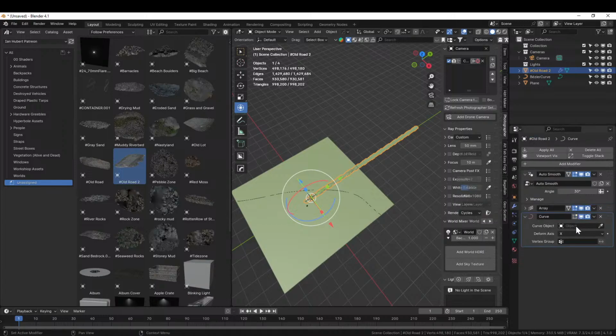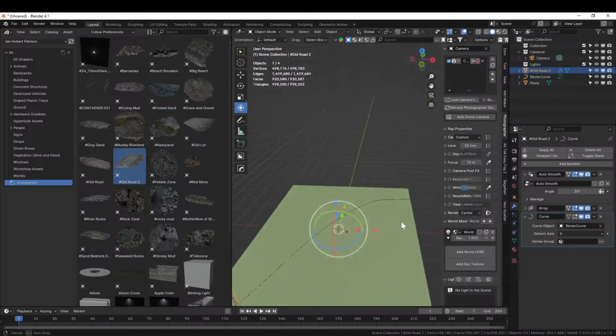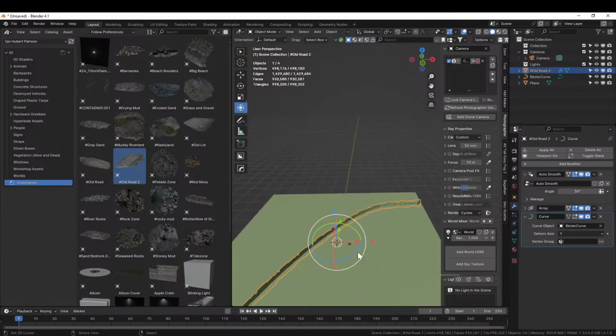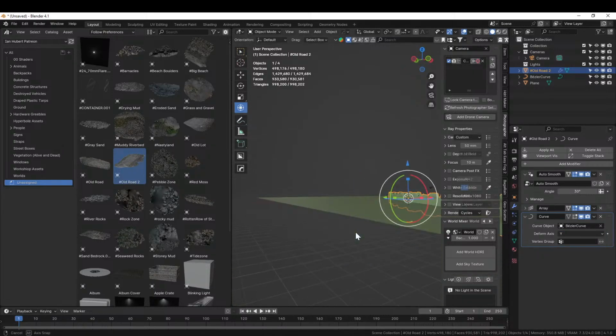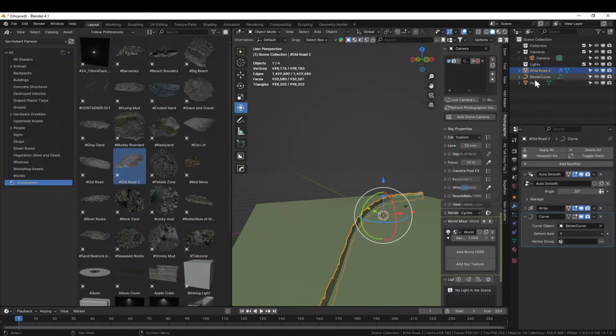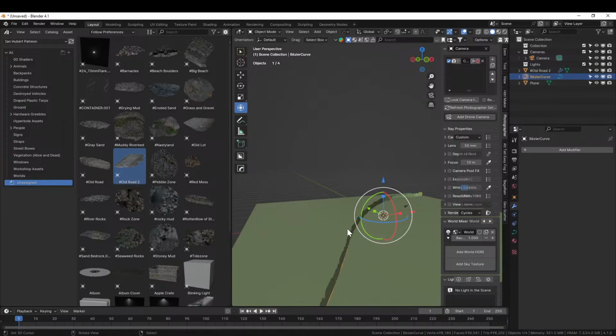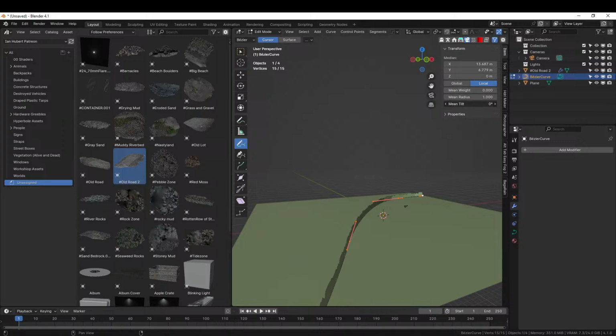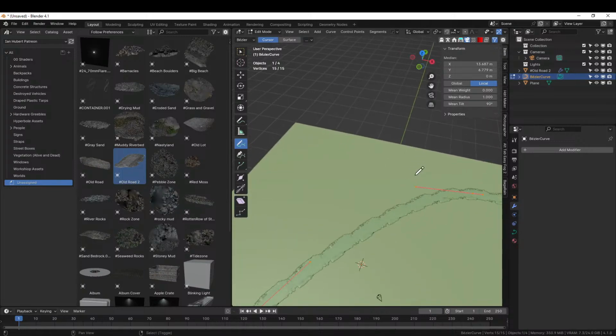What, to keep their origins the same? Is that what you forget, Michael? I often forget that too. Okay. Deform axis of Y. And we've lined up, but oh no, it's sideways. Yeah, we've dealt with this before too. It goes to the direction of the normal, and by default, then a curved normal sticks straight up. So we just come edit, grab them all, item, and tilt it 90. And voila, we have a road. I'll move this out of the way.